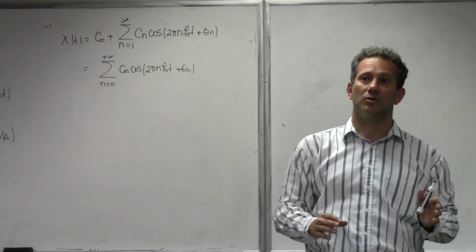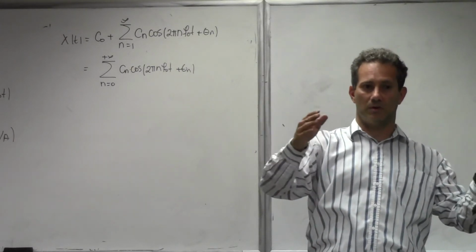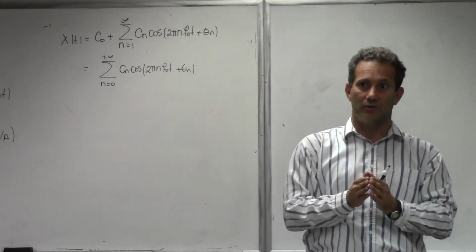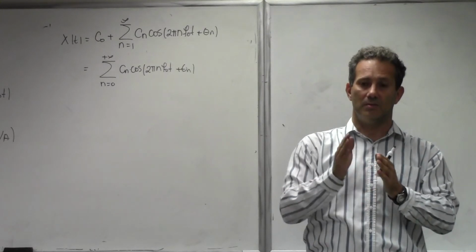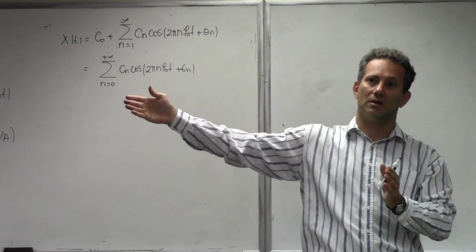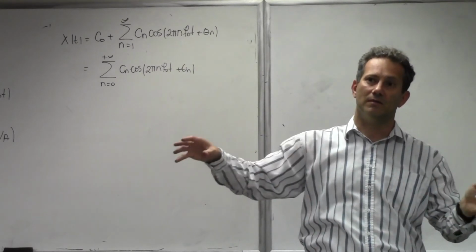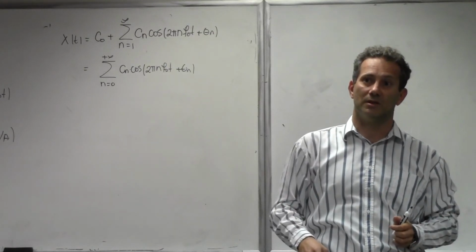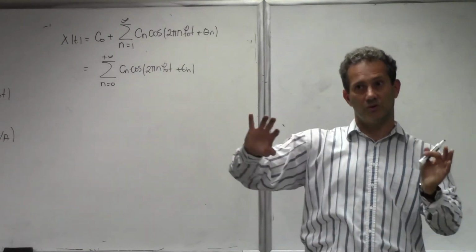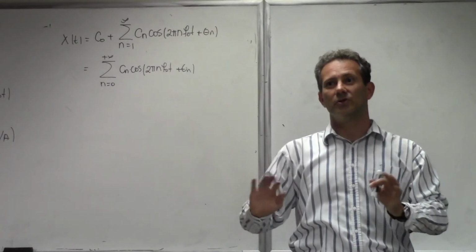What is harmonic distortion? If you have a nonlinear system, and then you run a sinusoidal through that system, then besides the fundamental frequency, you're going to get all of these other harmonics. Harmonic distortion is defined as the power in harmonics divided by the total power of the output signal. It's a measure of how linear your system is. So that goes into a slightly different area. Here we're dealing with linear systems, so there's no distortion.